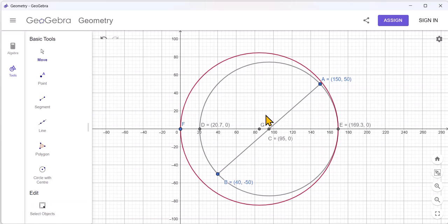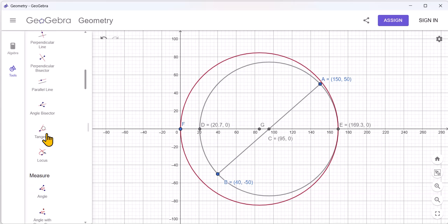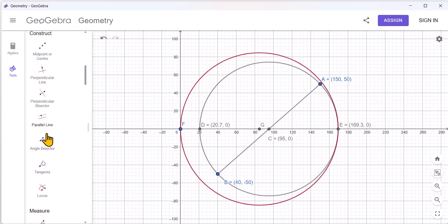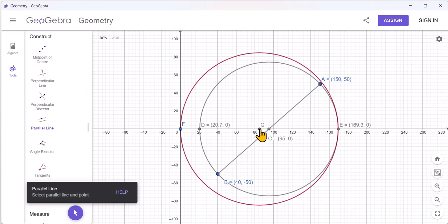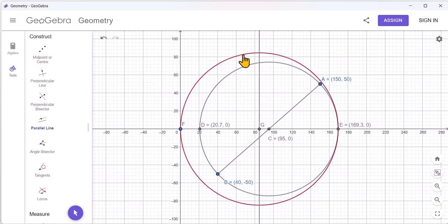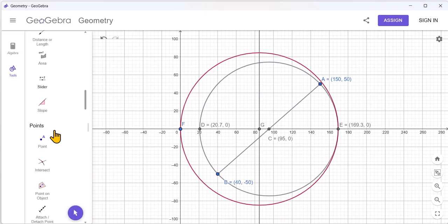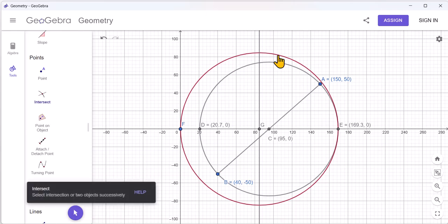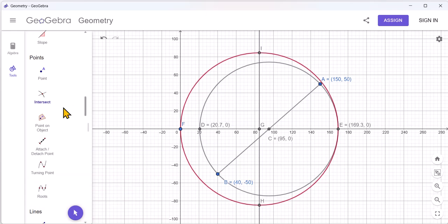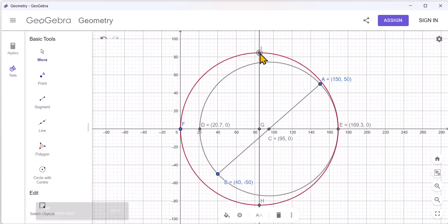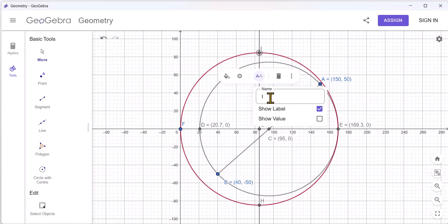So now I come and find my maximum shear stress based on the red circle, which is in the XZ plane, because this is my sigma 1, this is my sigma z. Now, if I want to do that, I have to draw a line parallel to my tau axis from point G and find the intersect of that line with the red circle. This is my absolute tau max.